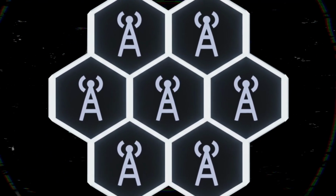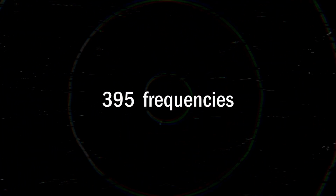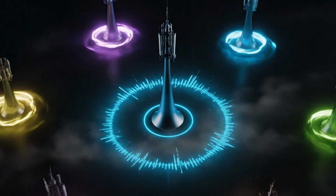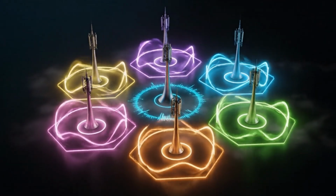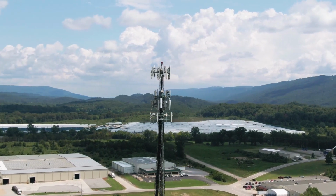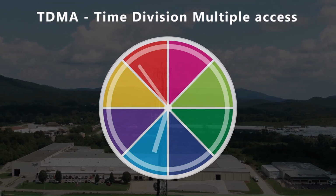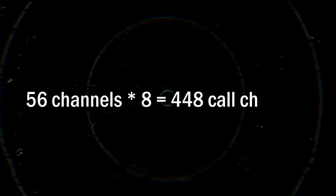Each cell site belongs to a cluster of 7 cell sites. So the 395 inbound and outbound frequencies are divided among these 7 cells, giving each site 56 channels. With 6 neighboring cells surrounding each site, no 2 adjacent cells share the same frequencies in order to prevent interference. However, 56 channels per cell site is still limited. To increase the supply, each frequency channel is split into 8 time slots, allowing multiple calls to share the same channel. Now each site can handle 448 call channels.